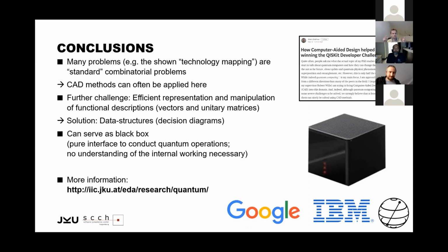And if you have multiple errors or certain other classes of errors, even then, empirically, we've shown so far that with just a couple of simulation runs, in many cases, you have no guarantee, but in many cases you will find the error. In the conventional realm, when you do simulation, you often have masking effects, and you need to find the right patterns, and often it's impossible to verify the equivalence of two circuits just by simulation because of masking effects.